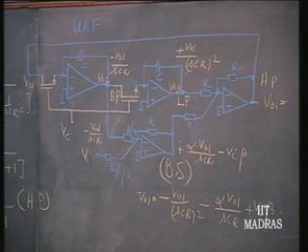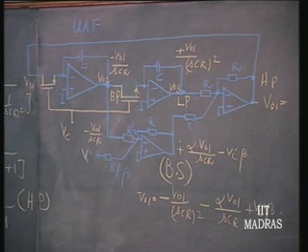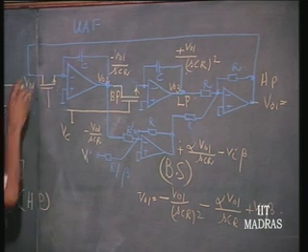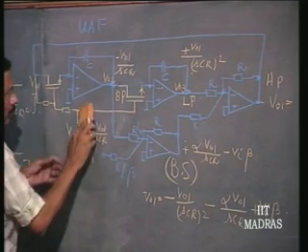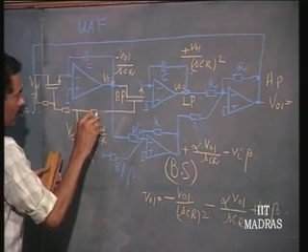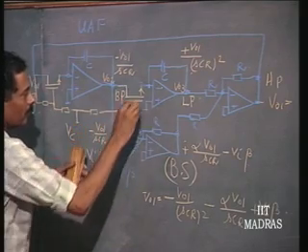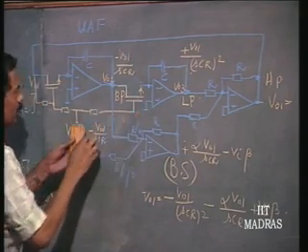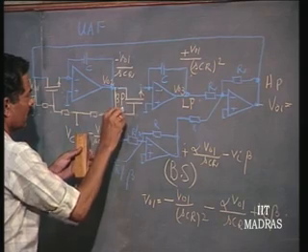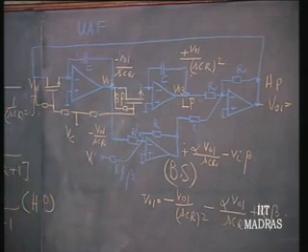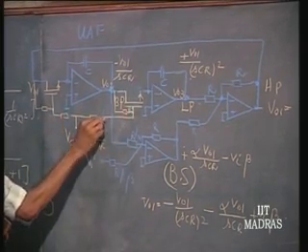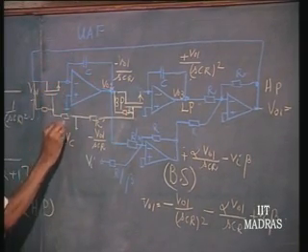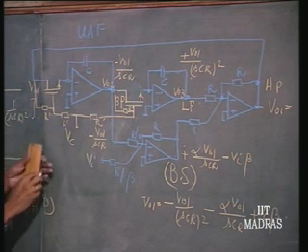If I use this kind of arrangement, it is not linearized. If you want to linearize that, you can do it by putting resistors, R dash, let us say, to distinguish from this resistance, R dash, linearizing resistors, and the control voltage is connected here.